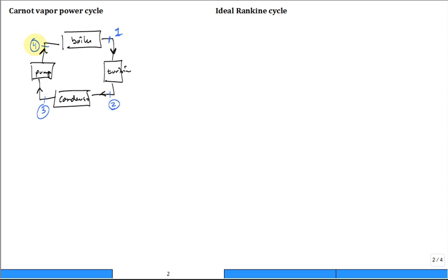And then often we analyze things like the heat added, Q_B. I put a lowercase q for the amount of heat added per kilogram of steam going through the boiler. How many kilojoules were added to each kilogram of steam? That is Q dot divided by m dot, the rate at which heat is being transferred into the boiler divided by the rate at which mass of steam is flowing through the boiler. That's lowercase q. True?